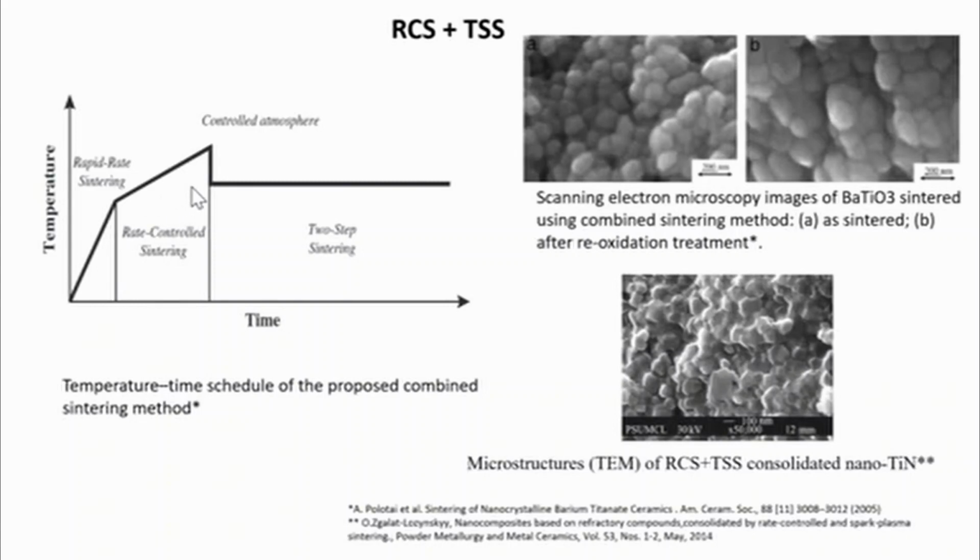the open porosity network loses stability, forming closed spherical and ellipsoidal pores, which are located in triple junctions. Splitting of cylindrical-shaped pores and localization of spherical pores are accompanied by extensive grain growth. Flexible control of densification during rate control sintering maintains an open network of pores at higher densities, 92-96% of theoretical, than in conventional sintering, resulting in a finer grain microstructure.